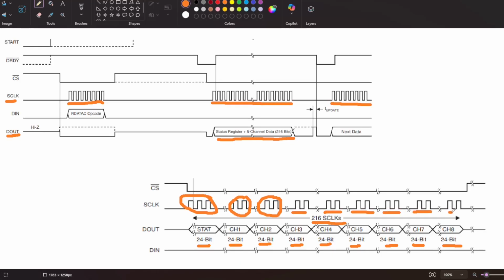And this is where the register table we saw earlier becomes useful. The datasheet tells us the register address, what every bit does, and what value you need to write. Our firmware then converts that information into the SPI bytes required by the ADS1298. And that's basically the idea of using the ADS1298 with a microcontroller.